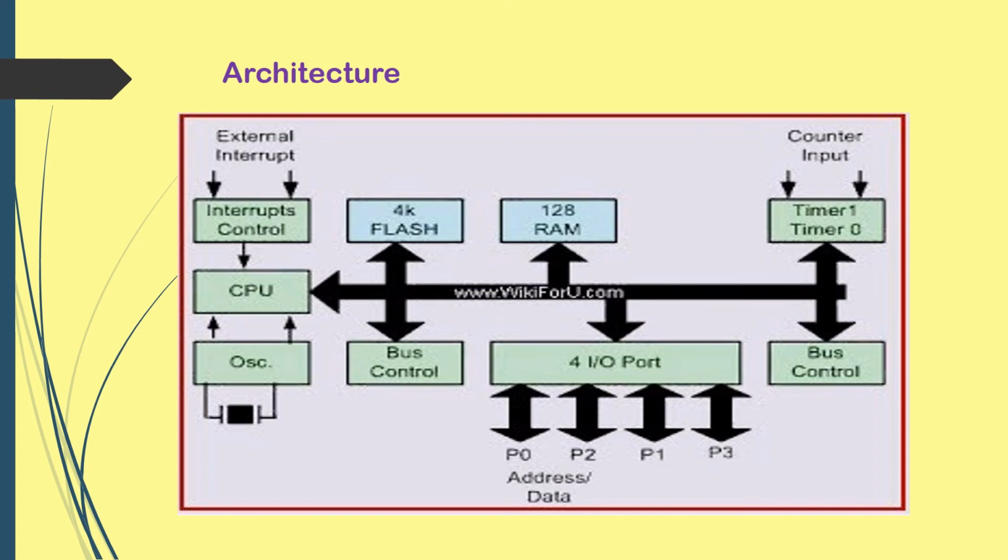Then registers: there are a number of registers, mainly A and B. These are the conventional traditional registers. Then there are the serial port data buffer, SBUF, the timer counter mode control register, TMOD, the power control, PCON, interrupt enable control, IE, timer counter control, TCON, serial port control, SCON, then the interrupt priority register, the data pointer, DPTR, and many more.